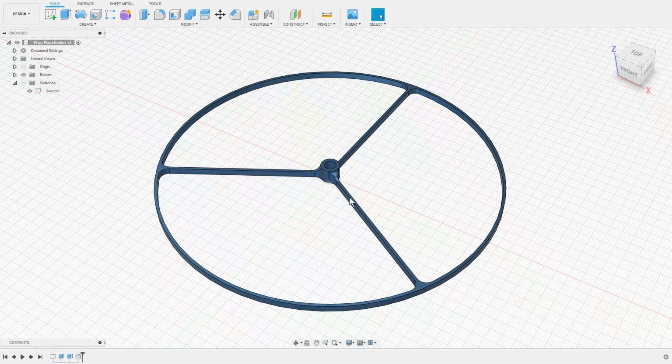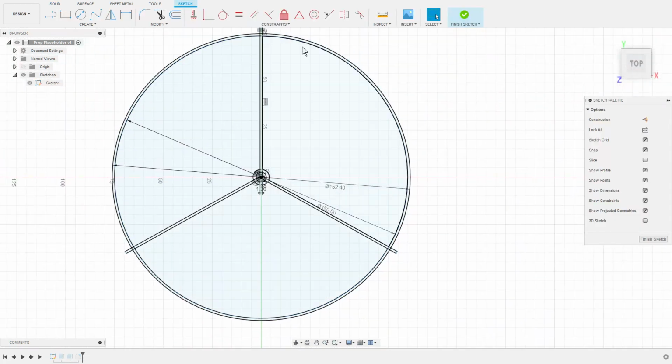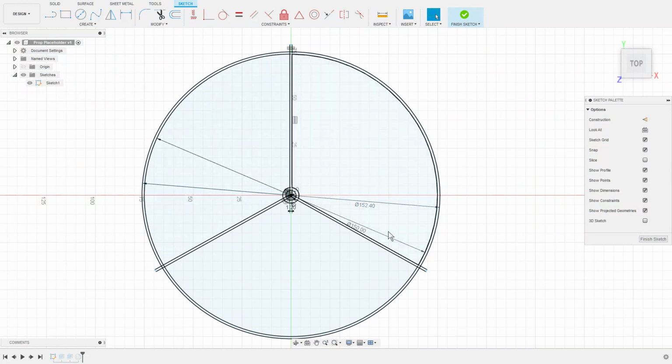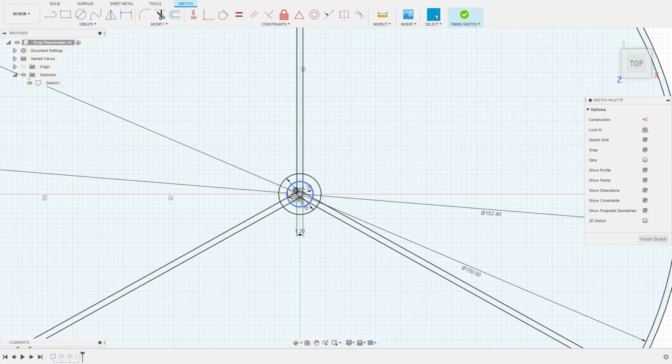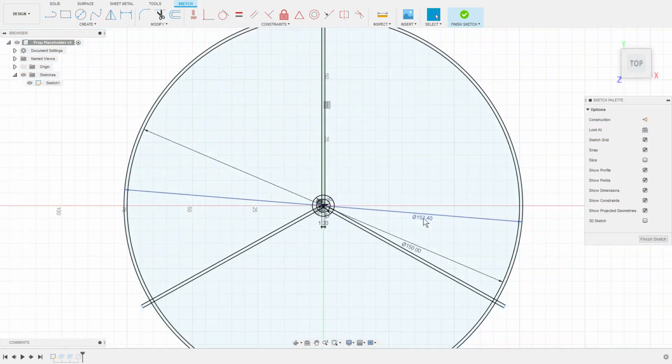Now, because this is going to be 3D printed, a lot of the dimensions I'm going to be using are going to be sort of base 0.4, in a way. In other words, they're going to be derivatives of the nozzle diameter of 0.4 millimeters that I'm going to be using. So if we look at how I drew this particular object, you can see that I just created a whole bunch of statically defined measurements for the geometry. It's a very simple project, and to change things, you could come back here and modify the dimensions, and that would work just fine.